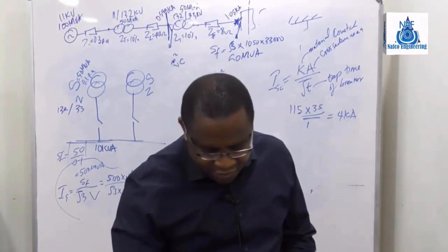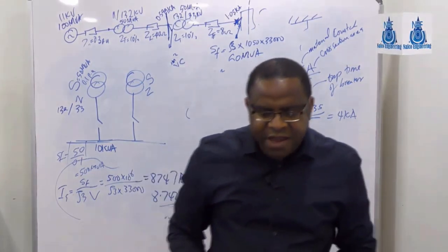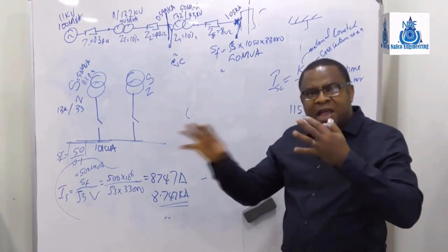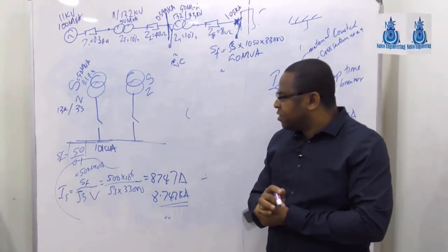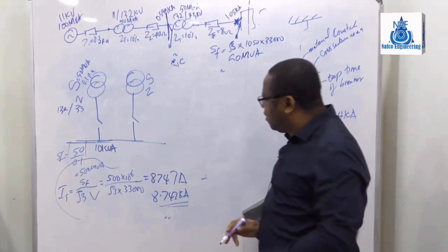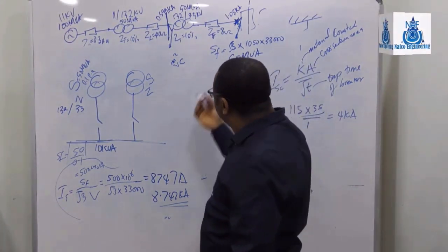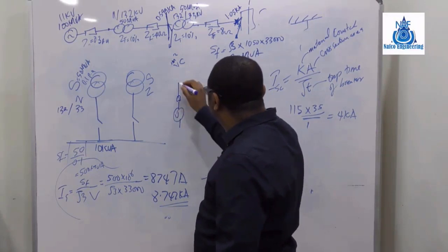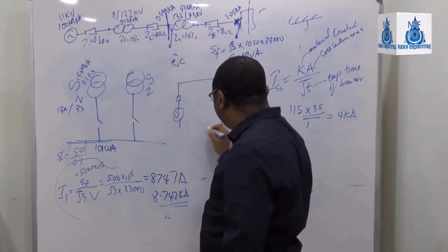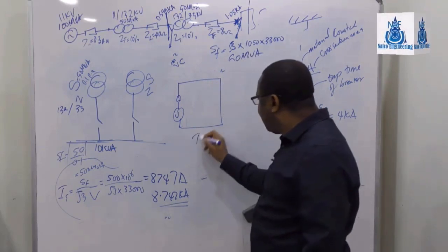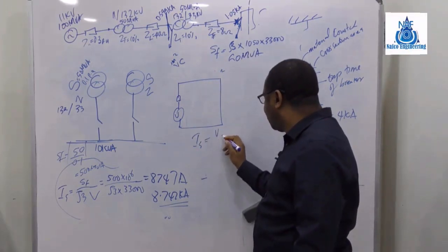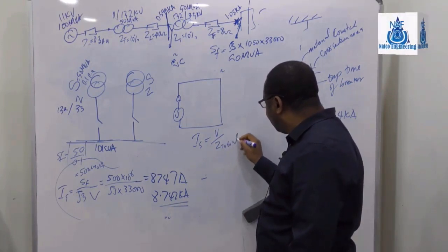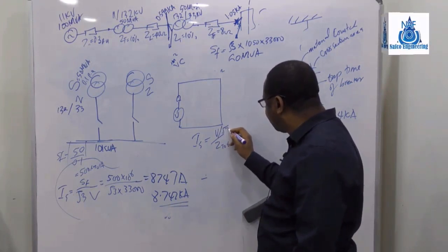All right. So now what again do you need to know? Because you need to know some of these basic terms. Now, if you check, let's say I have this impedance, and I have voltage, and I short this. If you get any short circuit, it is your voltage divided by Z total, but this voltage is a single phase in this case.